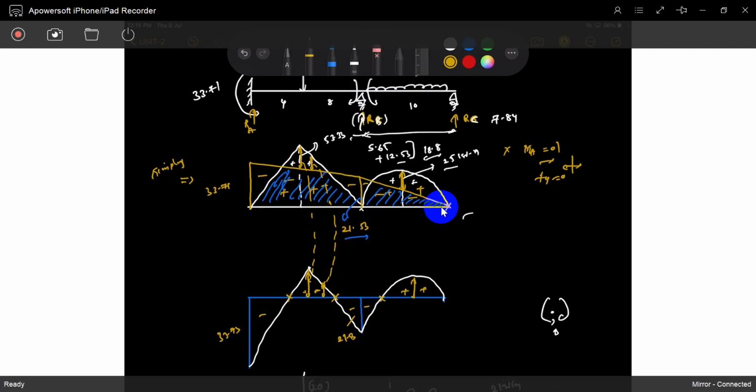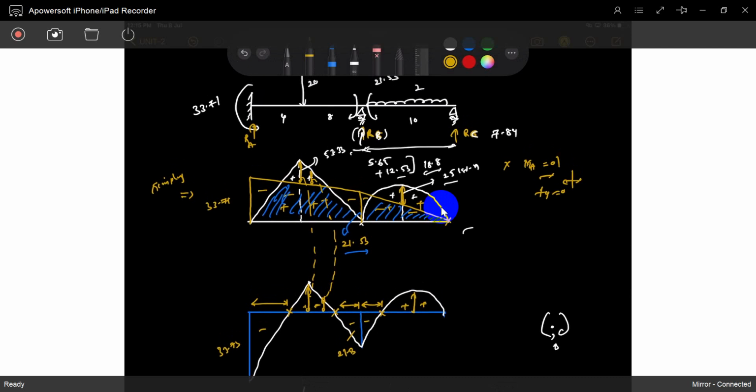If you are a designer, you have to find the distance between these two points, where the bending moment is going to be 0. Otherwise, no need. To just draw, you can freely draw like a free body. No need to find the distances. The curvature changes now, and changes again at this location, and it will reach like this.